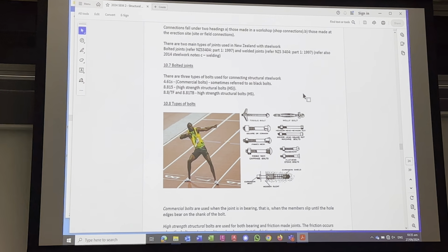If you have a slotted joint hole, the slotted hole looks a little bit like this, and there's your nut or your bolt, sorry. That bolt can go anywhere along here, and you can move it and the steel plate will still fit over the hole.